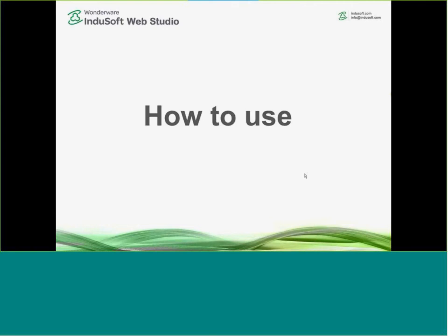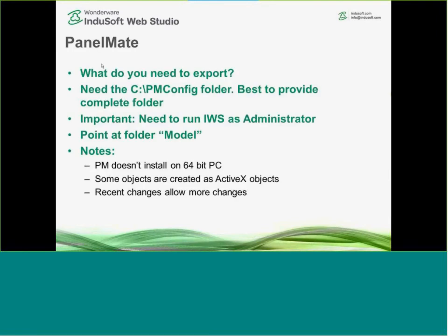Okay, so how to use these. Now this is the major section that I wanted to pay attention to, and I was surprised, I was going to focus and spend a lot of time on just the FactoryTalk import tool because that's kind of the latest and greatest from Rockwell, but it turns out, based on the longevity of some of these products, and now where they're at in their product life cycle, we're getting lots of requests to convert PanelMate and PanelBuilder32 type projects as well. So let's take a step back and take a look at the PanelMate.